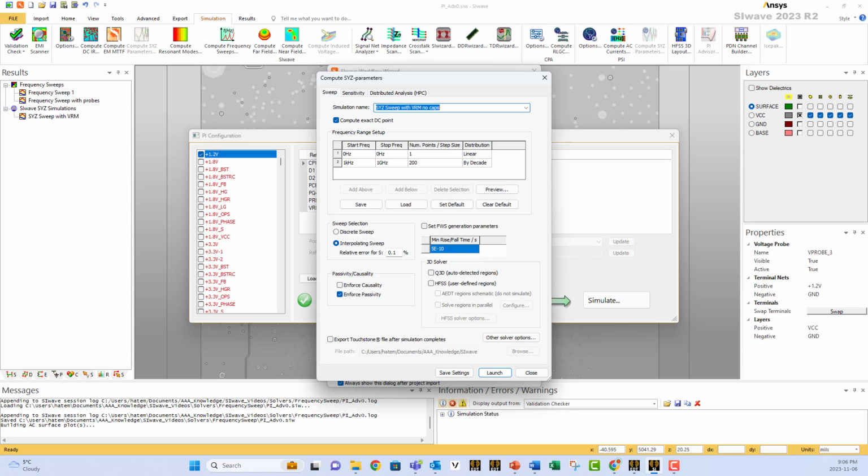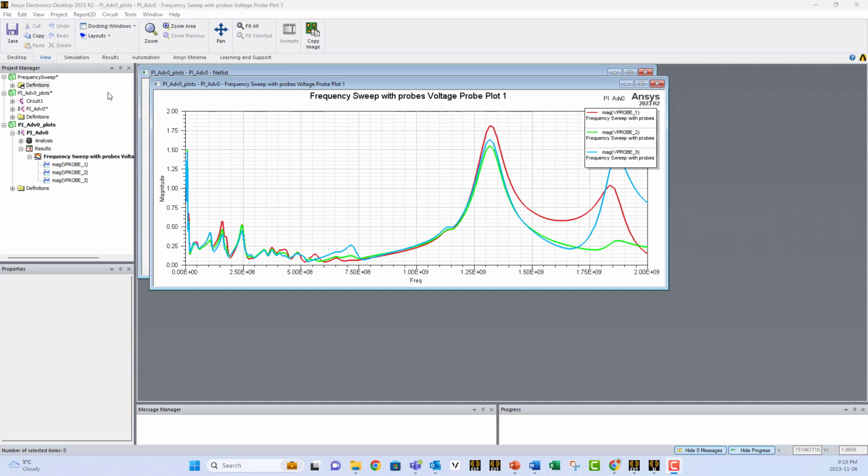It's important to note that the maximum frequency, this number, affects the rising time number, which is here. 0.5 over frequency is used to calculate the rising time. So we change this to 2 gigahertz. So the rising time now is around 250 picosecond. That's the minimum rising time we're allowed to use with a 2 gigahertz solution. So these 2 numbers are related. And we launch.